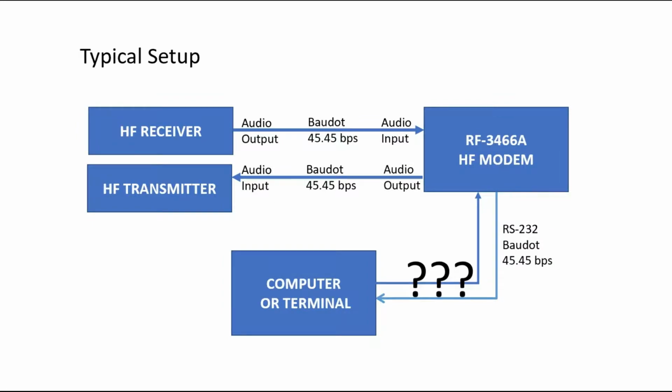The problem that we have is that there are no more computers or terminals, not easily accessed anyway, that will handle an RS-232 communication at 45 baud and with the Baudot character set. So what can we do about this? Well, this is what I've done.